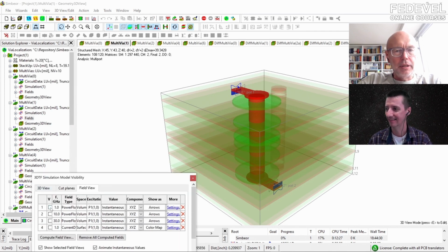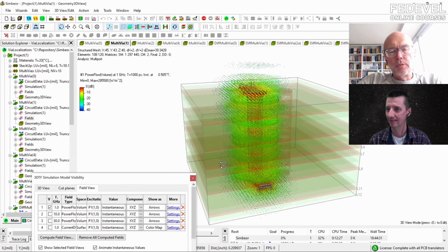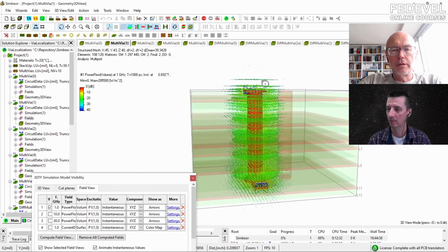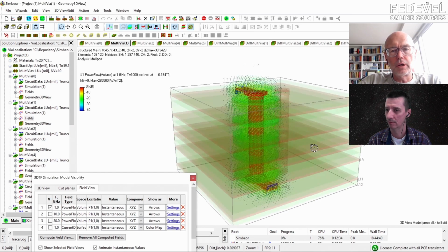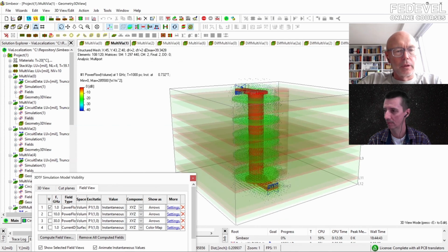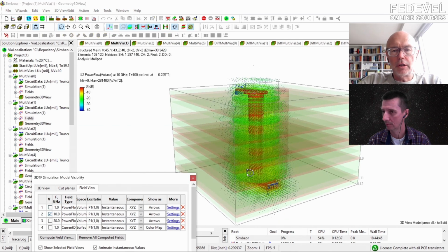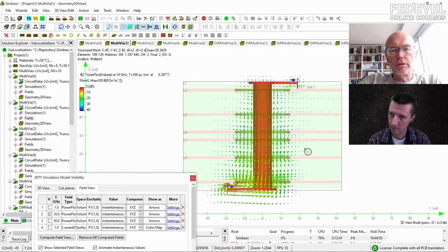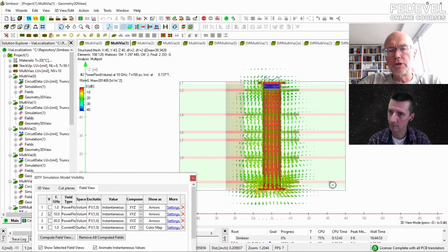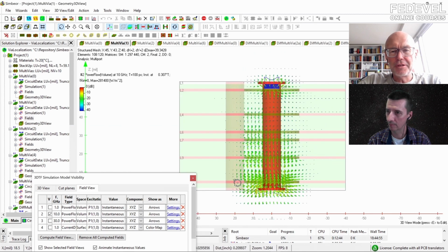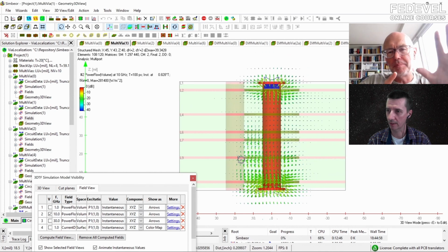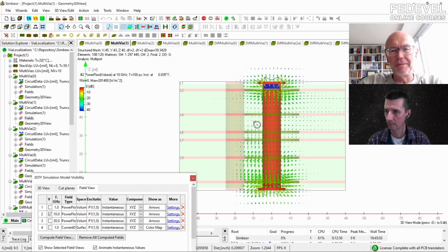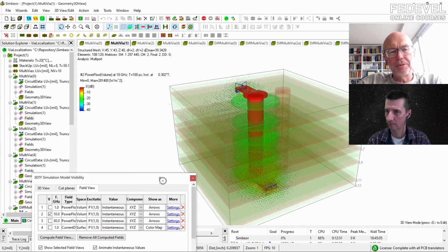With one via, at 1 gigahertz, we'll not see much difference. The interplane capacitance and the energy is localized pretty much around the via. At 10 gigahertz, you'll see some energy getting, to be more clear, you can see more energy getting this way than this way. So this via shield basically provides help. Return currents go through this via, but on this side you don't have it.